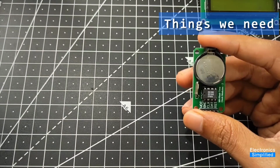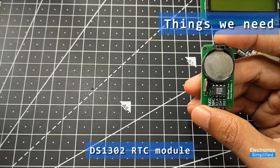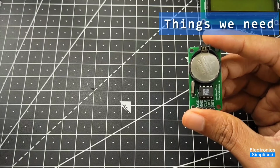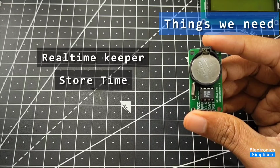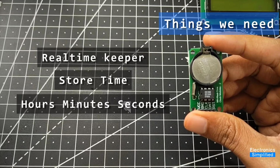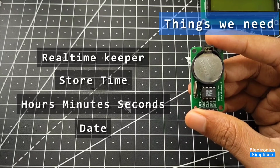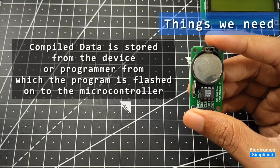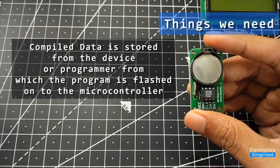We will be needing the DS1302 real-time clock module. Now this clock module is a real-time keeper. It can store time in the format of hours, minutes, seconds, and it can also store the current date. So how does it really store the date? It stores the date from the compiled form from where the code is being uploaded. It is called the compile date.